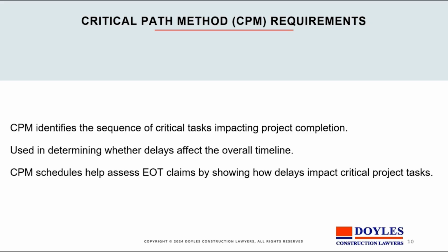The situation then is when you're putting in an extension of time or considering an extension of time, it's important to identify whether or not the activity was on the critical path. And that critical path can vary during the conduct of the construction period. It is to a certain extent influenced by events, and to a certain extent it's by choice.